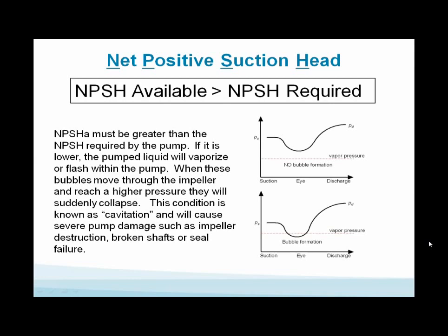We've got the measure of the pressure. That piece of S is the gauge pressure, the suction flange gauge pressure. And the pump flows from the gauge pressure to the eye of the impeller, and because we're changing flow rates and we're putting work to it, the pressure actually drops before it hits the eye of the impeller and starts going back up. And that pressure drop of a pump is the defined required NPSH of a pump. And that pressure drop, if it falls below the existing vapor pressure, will cavitate a pump.